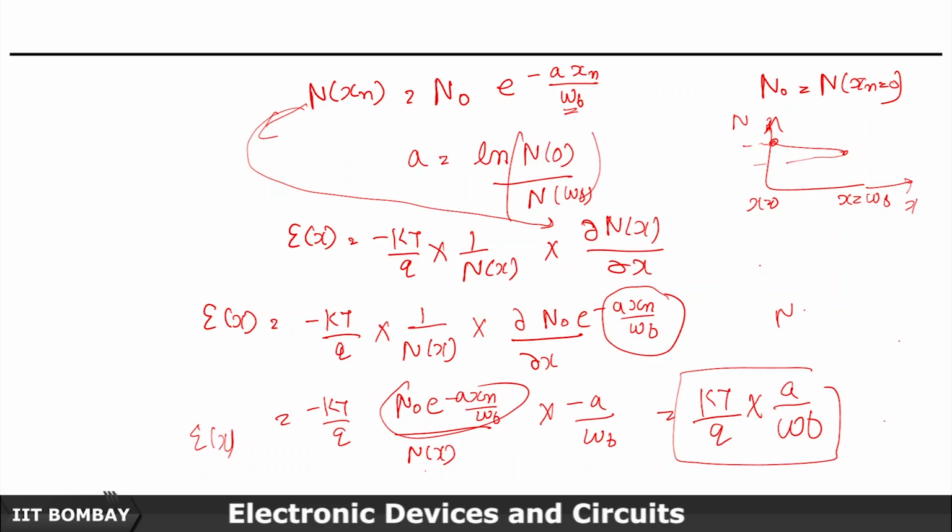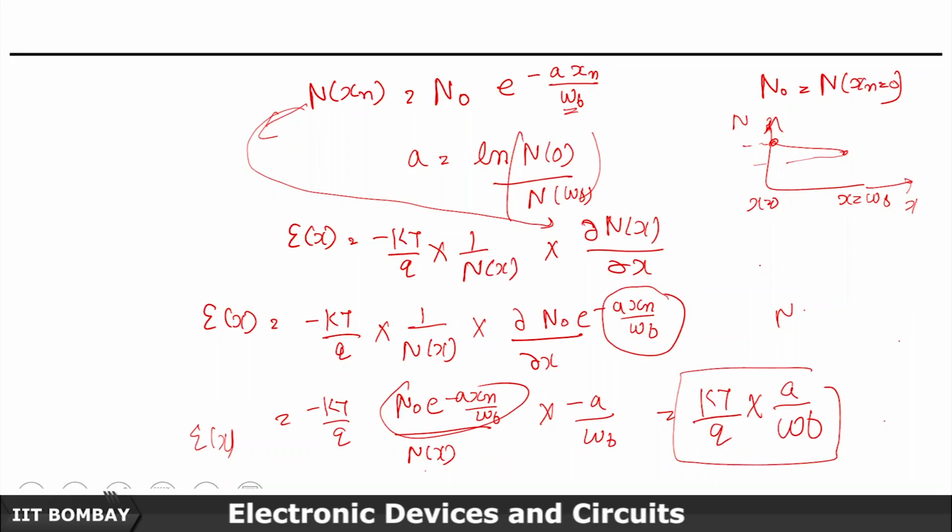Okay, that's the beauty. Of course, you can get different expressions based on this doping profile. So it's the doping profile which is the source of this inbuilt electric field. Now, since we discussed a generalized case, let's consider what happens when we have this grading in a PNP transistor or NPN transistor. Let's consider the PNP transistor, and say we have this concentration gradient.